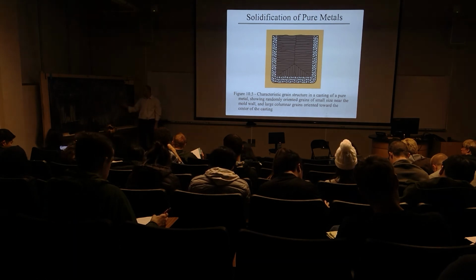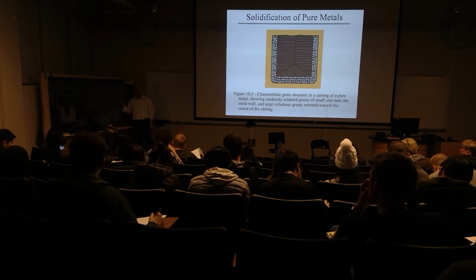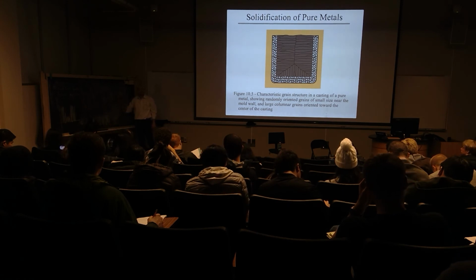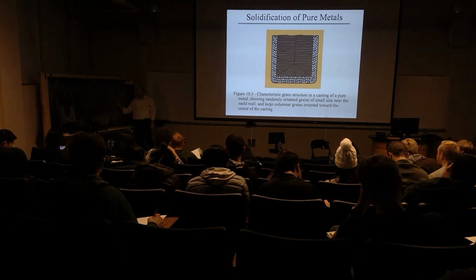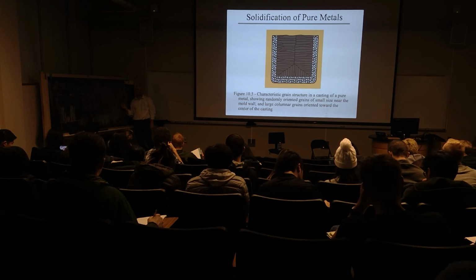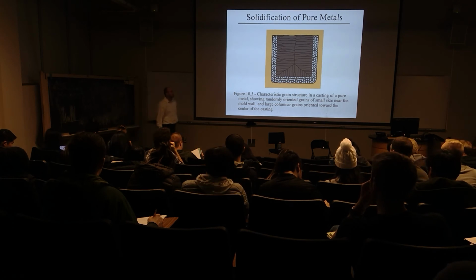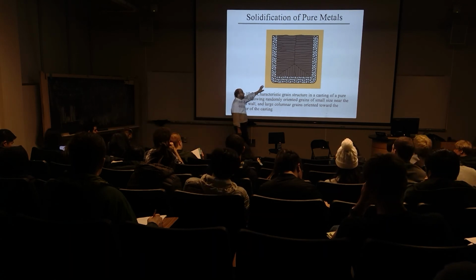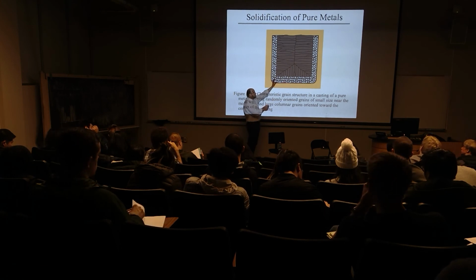And then what we have is an inverse relationship with the square root of D, and K is just what's called a strengthening constant. It's just a constant that's used as a curve fit in an experimental evaluation. So base yield strength plus an addition that increases as a function of the decrease in grain size. Okay, so when we look at this response, we know this is the weakest and this is the strongest.